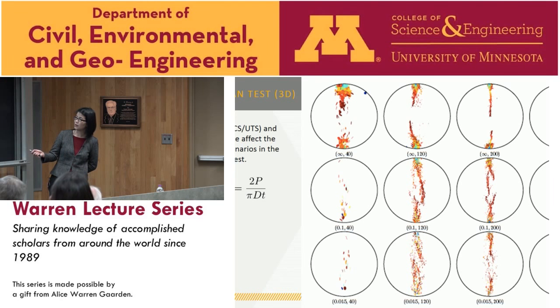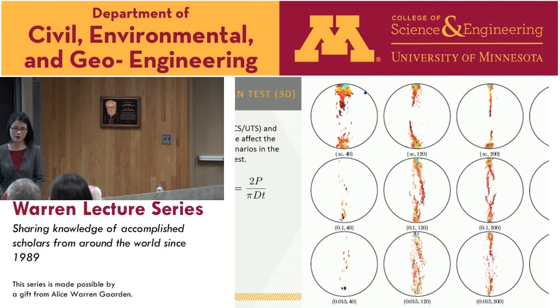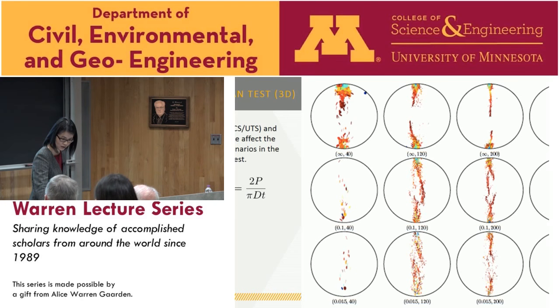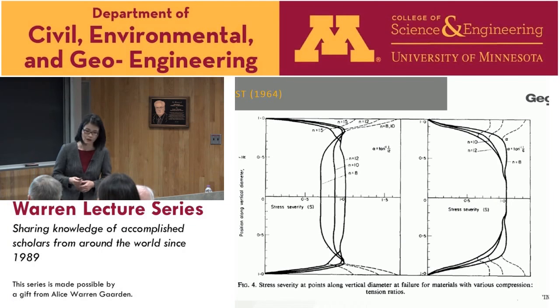And in the literature, people have tried, actually in concrete with cement, to have a sample size of 3 meters in diameter, in the hope of figuring out the size effect by going bigger and bigger. But really, if you look at the mechanism over here and how the tensile stress depends on P and D, going with a large diameter of 3 meters is really not helpful. You are going from one mechanism to another one, and so you are really no longer in the valid region for Brazilian test interpretation.